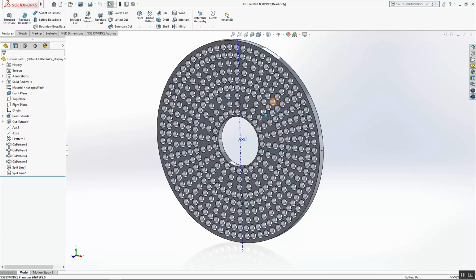When we use tetrahedral meshes, there's a little bit of non-symmetry. Well, there can be a lot of non-symmetry that gets involved, as well as the fact that sometimes you have tetrahedral elements that will collapse on each other. They can also be a little bit more stiff than brick elements. Because we're using a hyperelastic material, we're also going to use the H elements that are available inside of SIMULIAworks, which are more well suited for hyperelastic materials.